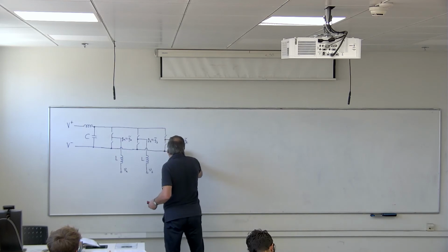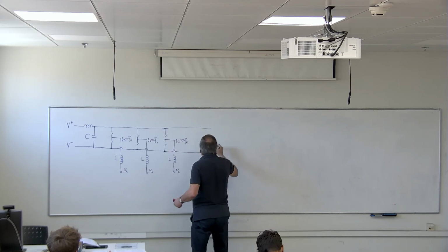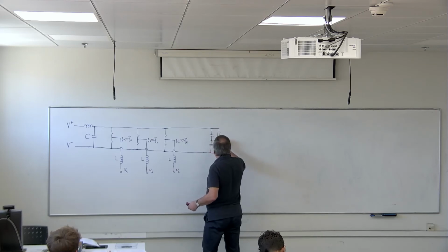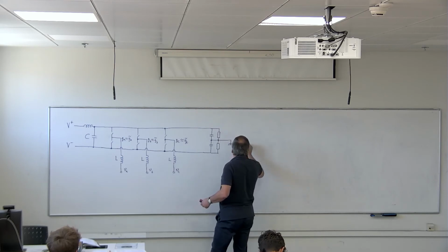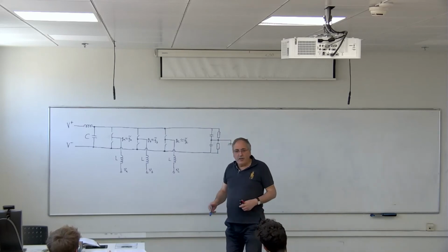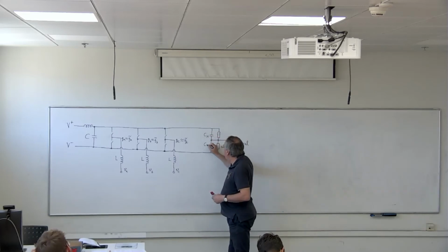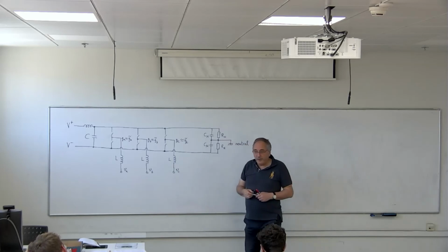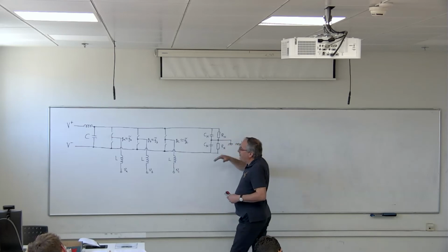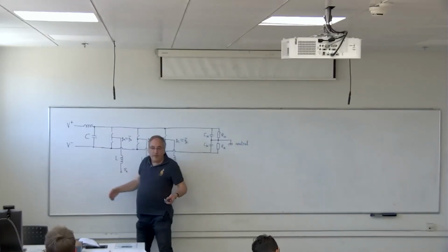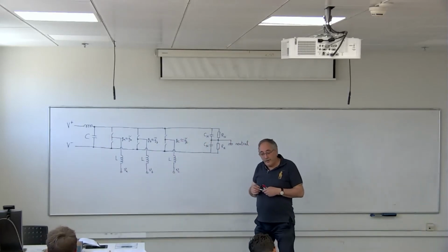There is a solution for a very weak neutral current. We can put here 2 capacitors and 2 resistors in parallel, and say that this midpoint here is our neutral. These resistors we choose large so that their power consumption will not be important. These are the neutral capacitors and the neutral resistors. The role of the neutral capacitors is to keep the neutral line stable with respect to V plus and V minus, so that it will not drift, let's say, very close to V plus or very close to V minus, which would prevent the inverter from properly functioning.